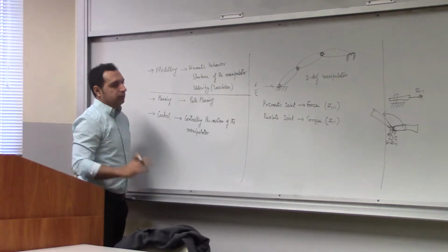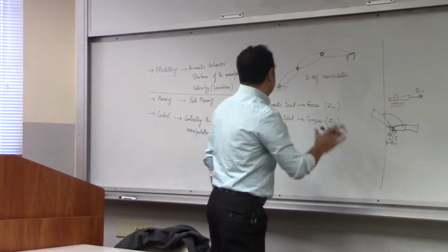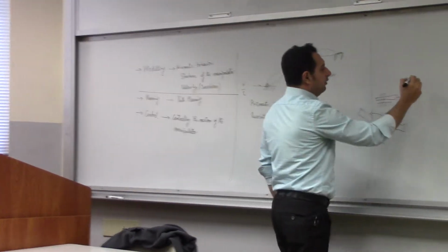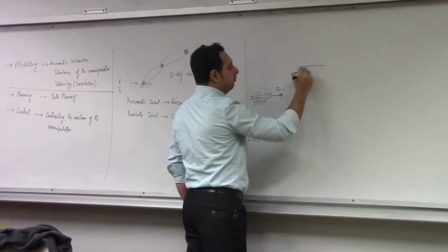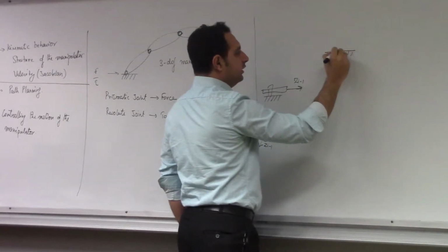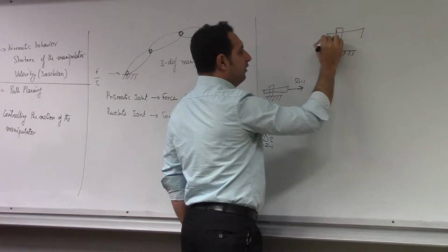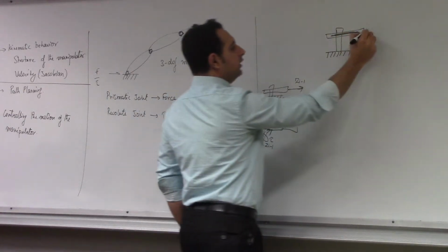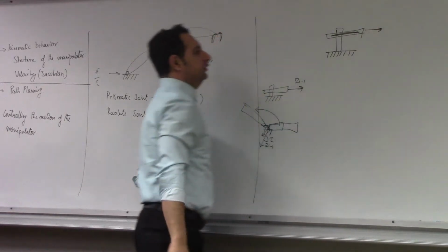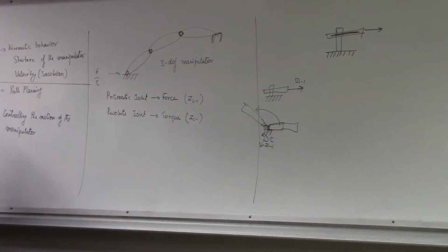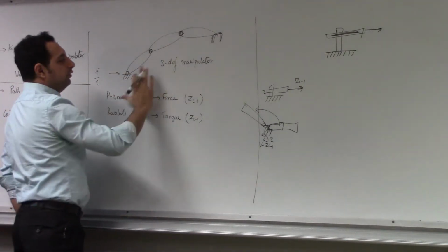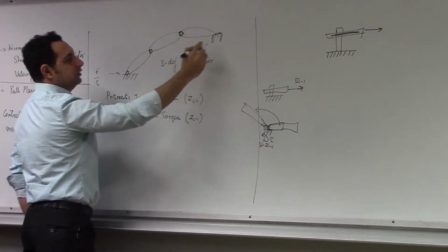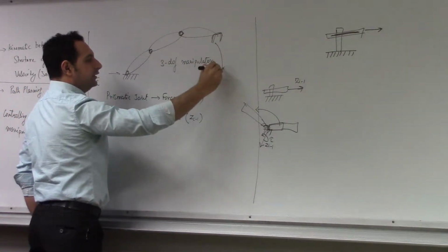All right. Now, if you study systems, normally if you have one actuation mechanism, a single joint like this, then you have a single system which is single input, single output, because you're only moving this in one direction or 1 degree of freedom. Now, in this case, you have 3 joints. So when you do a control loop, you control each of the joints simultaneously, because that will lead to the manipulator moving in some direction.